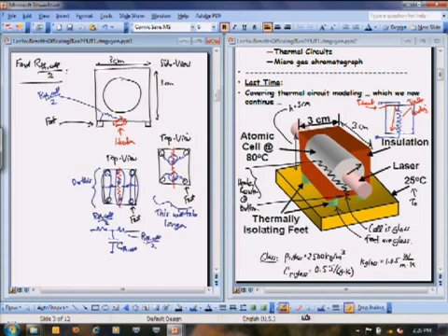So to half the total thermal resistance that you go across the whole cell. Okay? And you notice I'm keeping everything towards the bottom here. I'm going to ignore a lot of the stuff at the top. Right? And that's because part of our assumption from the beginning was that there was vacuum everywhere around this. So if there's vacuum everywhere around this, and I've got heat here, is the heat going to want to flow up to the vacuum? No. Right? Because this foot here is going to thermal ground. So this point right here, where my feet are, that's thermal ground. That's where the heat's going to want to flow. Okay? So let's now do the geometry of this problem.